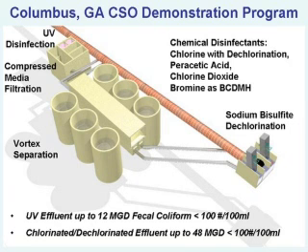diluted wet weather loading. As a tertiary filter, the filter has been tested to show that it gets down to below 1 milligram per liter or below 1 NTU, whether those samples were just what's coming out of the clarifier or spike samples where you add return sludge to that testing.